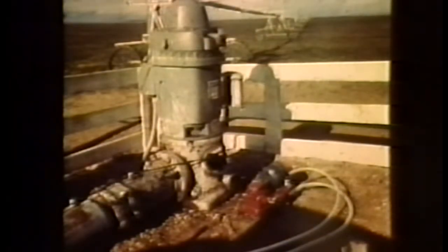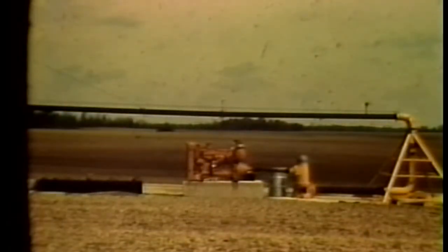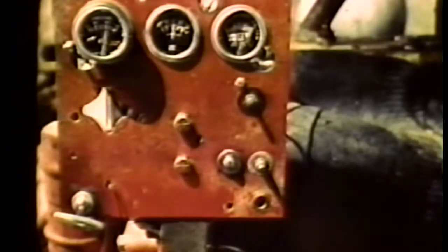The pumping unit takes water from the source and makes it available under pressure to the irrigation system. It may be driven by either an electric motor or by an internal combustion engine. Power units are generally equipped with safety shutdown controls that monitor the pumping unit. The safety shutdown controls for an internal combustion engine monitor the oil pressure, water pressure, and temperature of the power unit.